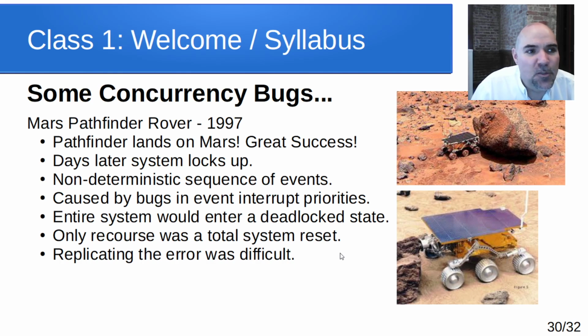They had this situation where something could lock something out, and then another event could happen, which would then have to wait while the bus was locked out. That thing would have realized it happened, and the bus was already locked, but it would enter a state while the bus was locked, waiting for it to be unlocked. And now you have this problem where the whole system locks up.